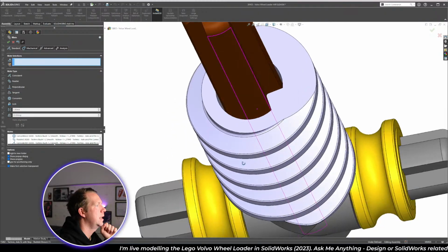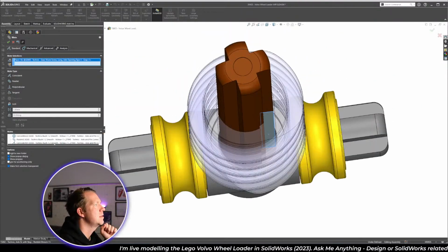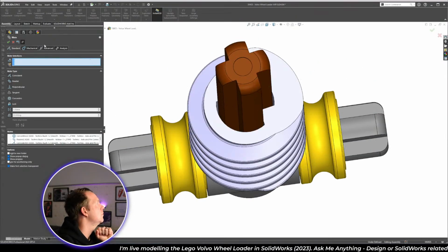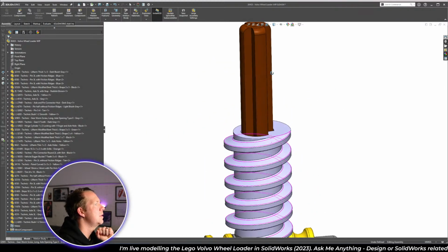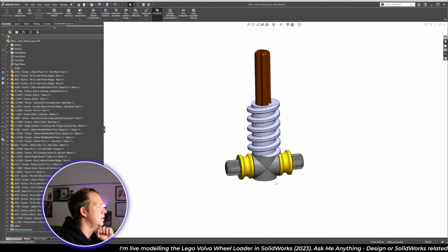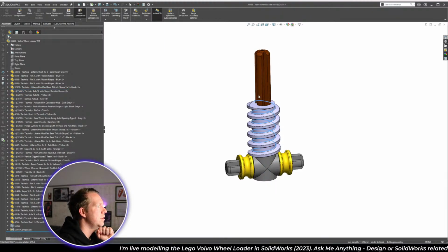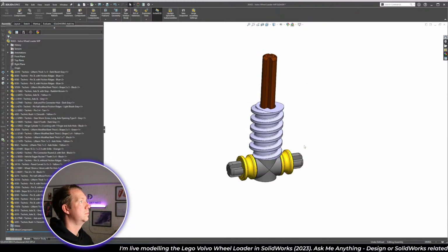And then to get it to rotate correctly, I need to do a mate for these 2 faces. And then later, once we fix, let's say, this part, we'll find that this one will now rotate. Right now, this one's rotating. This one's fixed. Let me change it. So I can make this one fixed, this one float, and now this can rotate. Cool. Save. Keep going.